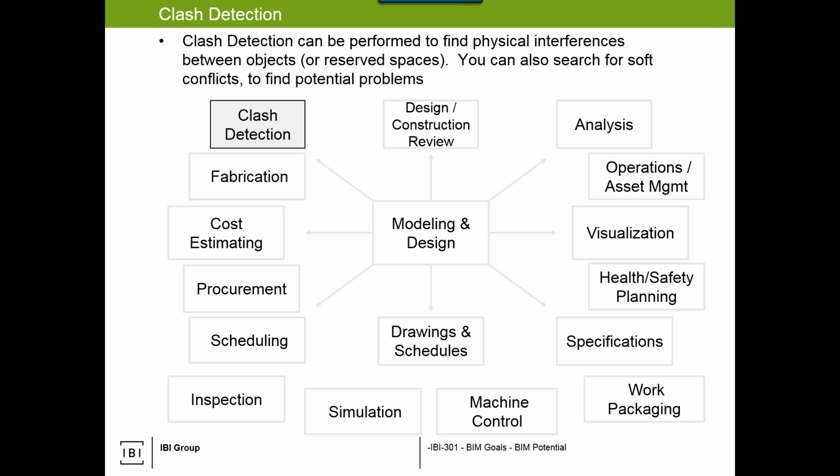If there's a beam sitting on a column, it may tell you that's a conflict, but you may have to identify that, hold on, don't tell me those because beams are supposed to sit on the columns. Or if you have handrail that's embedded inside concrete, well, you've designed it to be embedded, therefore the handrail post inside the concrete or the concrete curbs are not conflicts.